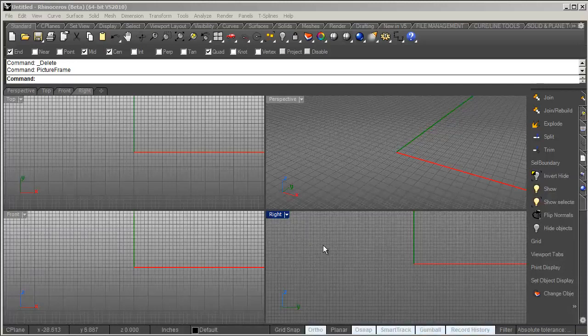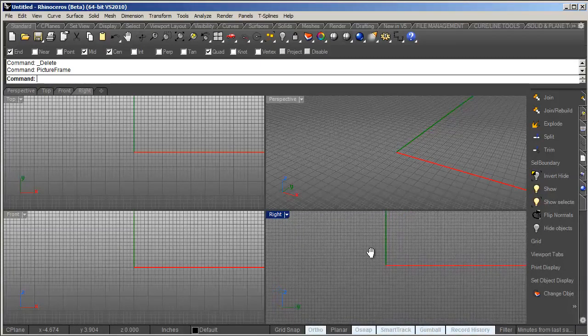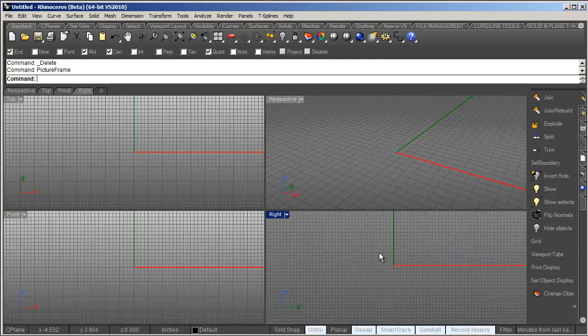Now, the first thing you want to do is go through in Photoshop and try to clean up whatever photo or whatever drawing that you're bringing in. If it's a blueprint and you've got something that's drawn fairly cleanly, such as an aircraft, which is the example I'm going to bring in today, you want to go in there and preset them so that they're already cropped to the correct length. And they really want to be the same length. If it's the side view and the top view, they want to be the same length. It'll be much easier to fit everything together. And I'm going to show you how to get everything scaled in here.